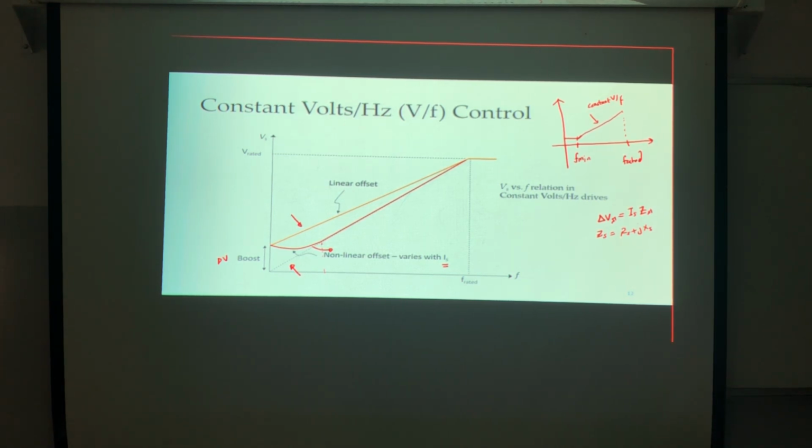So between the minimum frequency and the rated frequency, the relation is constant V over F. So the flux is constant at the rated.